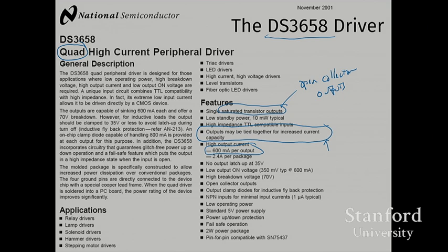You often have a case where inside the chip, inside the package, there's 4 different electronic elements. They each have 4 different values of the output voltage in the low state or other parameters. If you tie the outputs together and turn them all on, they won't necessarily share current equally. And the problem with that is that one of the outputs may be forced into operation above its specifications, and then bad things can happen that we've been talking about the last several weeks.